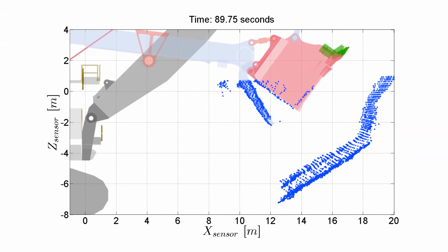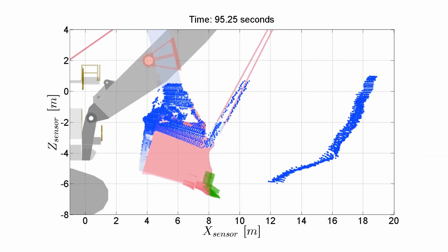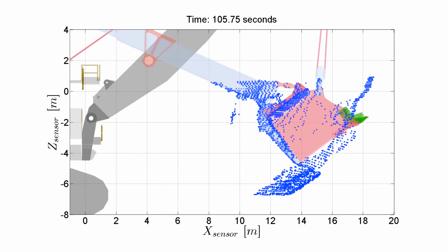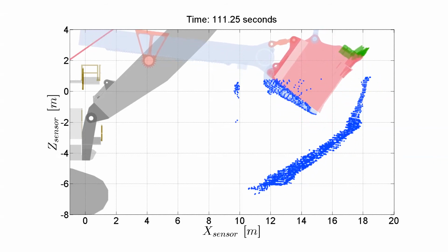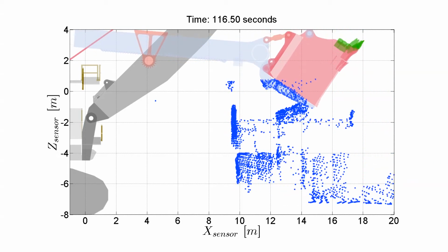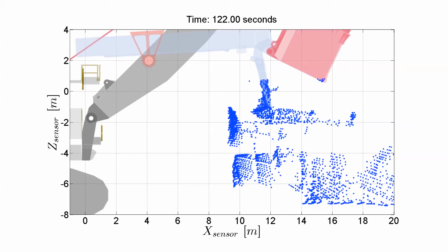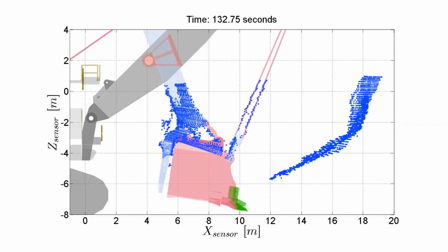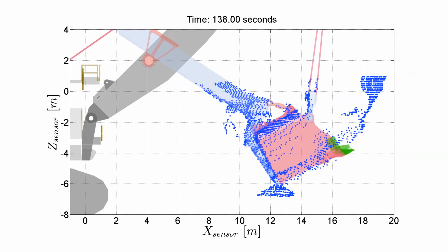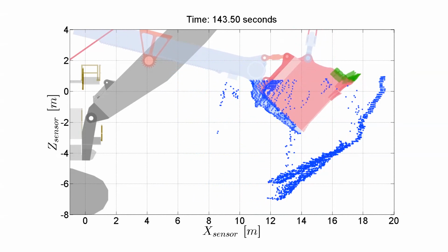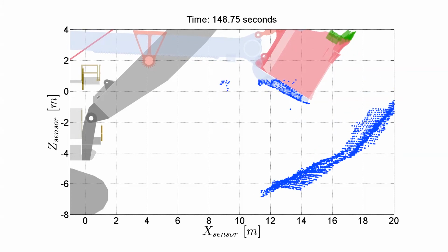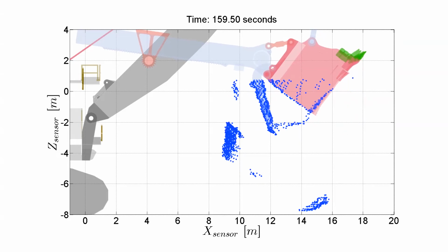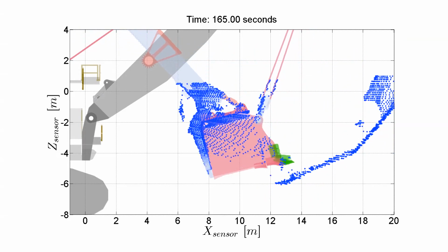And that's it, actually loading a haul truck. So I'm estimating the pose of this. It gets a little bit lost down here when you don't get much data on the door. It opens up a little bit, and up at the top as well, it opens up a little bit because there's just no data on it. The LiDAR was put here to find haul trucks, not to find dippers, and I looked at the data and said we could probably find dippers with that, so it really wasn't located for this problem, and we would do it a little bit differently. We're actually doing it now on another project. This is a P&H shovel. We're now doing it on Caterpillar shovels.